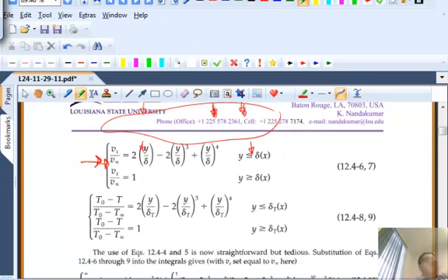And as you pointed out, what you need to do now is assume a velocity profile. We did this with a cubic velocity profile, I believe, when we looked at the one common integral analysis for momentum thickness. The velocity profile is arbitrary. You assume something. So in this example, he shows you one with a quartic profile, a fourth degree polynomial. Okay, and y is the distance in the vertical direction, and delta is the momentum boundary layer thickness. So as y goes to delta, the velocity field goes to the free stream velocity, that is Vx over V infinity goes to 1.